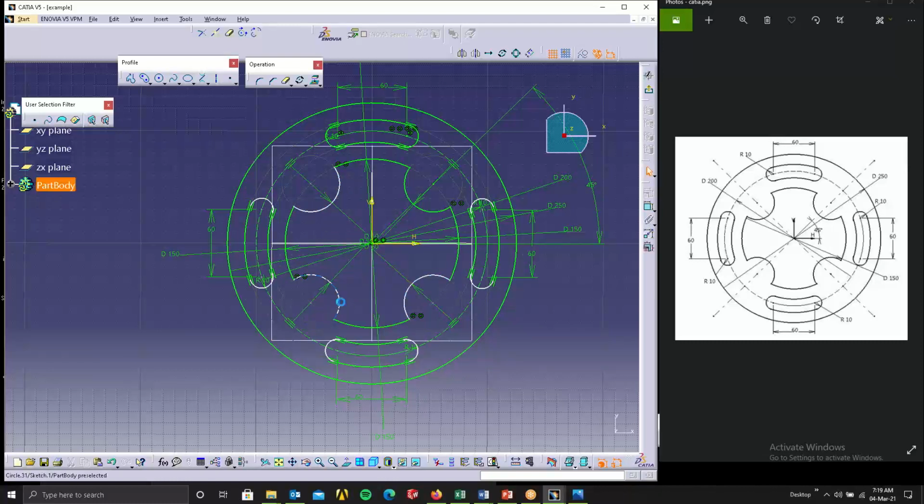Now just try moving this. So this is moving like this. This is the main problem. So what I can do is double click on this. If I give, this is not of use. I have to give the distance. Double click this to this distance. This to this one changed, I believe. Only this position is changing. So what I can do is this to this vertical line, this to horizontal line, and this to horizontal line. That's all okay. So you can see it's already constrained.